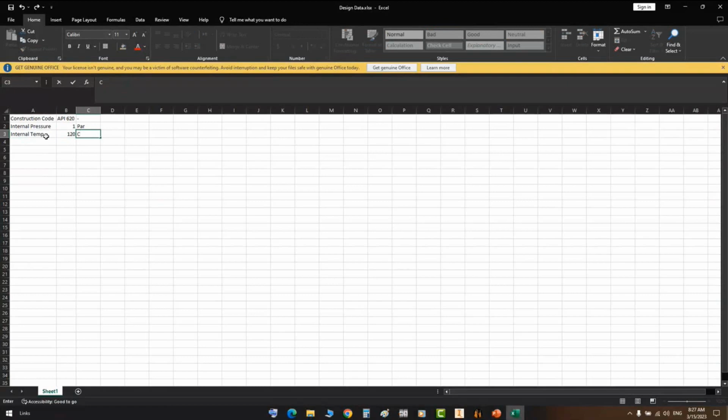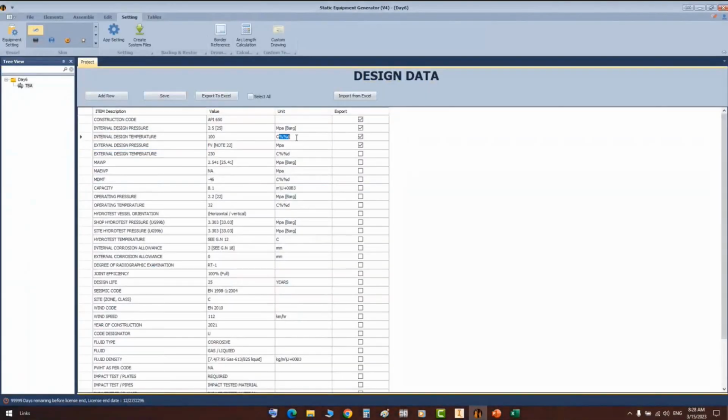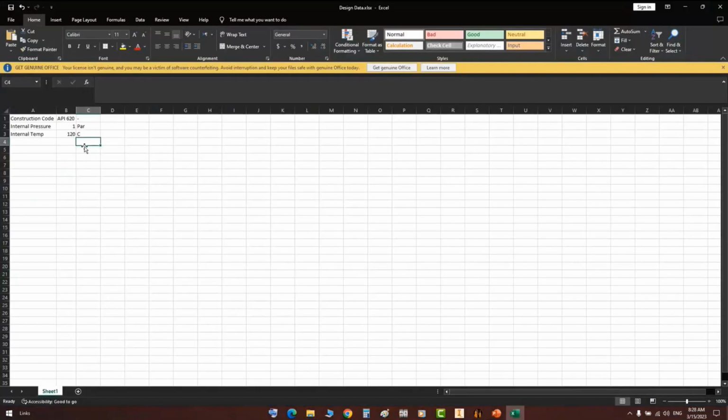And for the Celsius, to make the degree mark after the Celsius, you can figure that from here, you can detect that it looks like in AutoCAD. To make the degree, you will need to write percentage, then D as a small character. So you will get the degree when you export it to the Inventor drawing. So from here, let's write it like that. And let's say capacity.